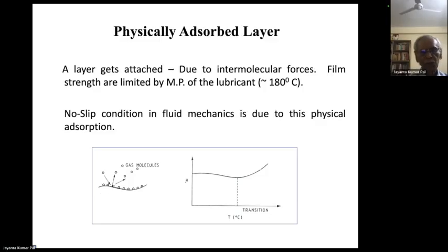Now, we must consider this very carefully, because during rubbing, heat is generated, and this increases the contact temperature. Exact contact temperature can be very high at the peaks of the asperities, but the average contact temperature will be tolerable, not in the thousands of degrees centigrade.